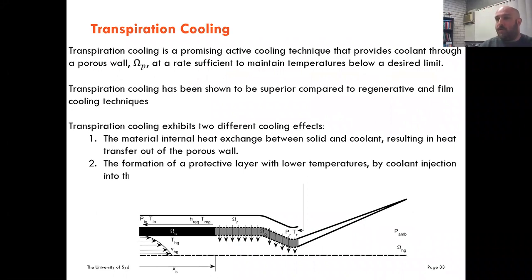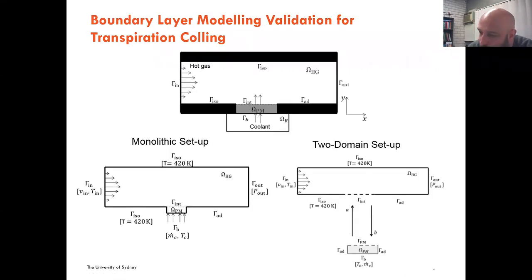Now, a second problem I wanted to introduce to you, which has an extra complication of having temperature in there, is transpiration cooling. Transpiration cooling is a nice technique to try and improve the efficiency of combustion, where we've got cool air being drawn from the outside. And as long as the lining of your combustion chamber is porous, it will get drawn through the porous material, and it will create a nice coolant layer around the structure, so you can run the inner part at a much higher temperature.